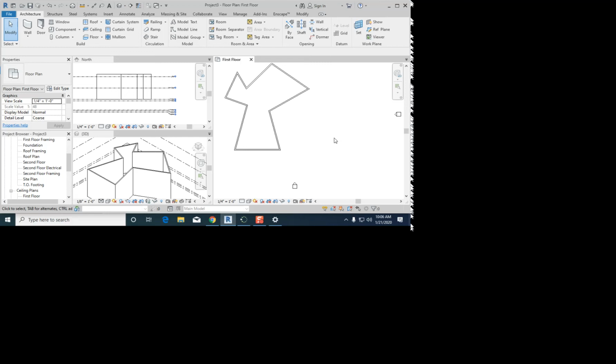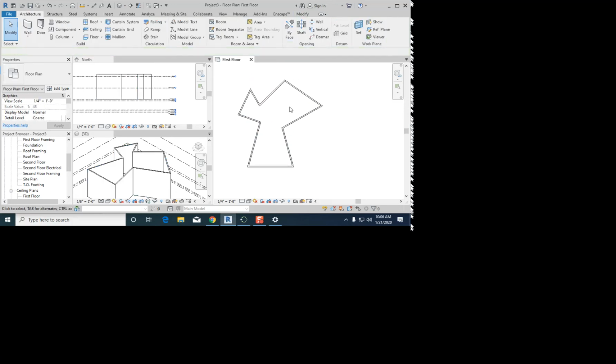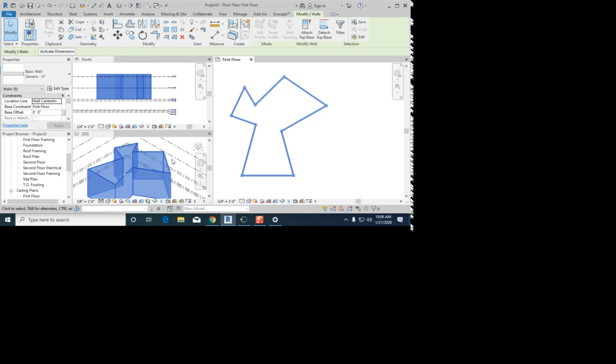Okay, hover just means you put your mouse over something. You don't click, you just hover. You're kind of creepy, like, hey, I'm gonna come stand right by you. When I hit tab, all the walls that I drew in that segment are now highlighted, and then when I click, then they are selected. So take a look at my screen one more time and see the graphic difference. Hover, highlight, tab, more highlighted, click, selected. Okay, let's do that together.